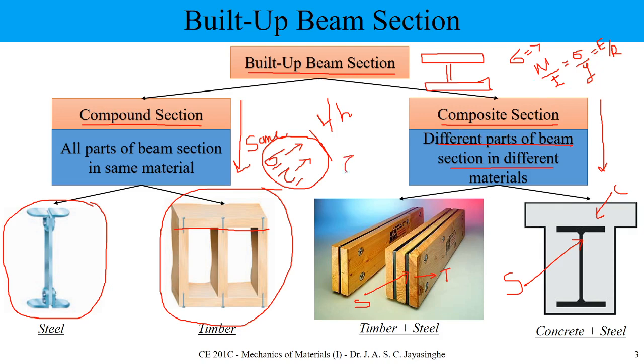For shear, the shear stress is tau equals V Q over I t. These equations can be used without trouble if we have a good connector, with 100% good connection within each layer. That means we are not expecting any sliding between those layers. If we have zero sliding, we don't need to worry, so we can use it. So I will remove these things.